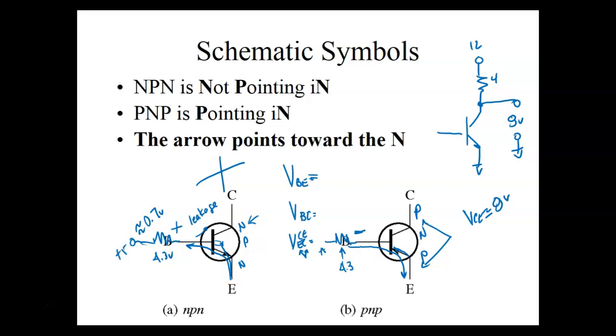Now you're saying, okay, here I've got all these electrons moving, and I'm looking for a positive. Up here on this collector is a big O positive, not a little positive. It's a lot more positive than the base. The base is sitting over here at 0.7. That collector might be sitting at 15 volts, and those electrons are looking for a positive. So about 99.9% of the current flows through there.